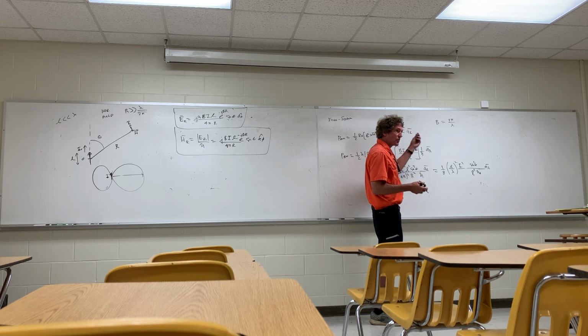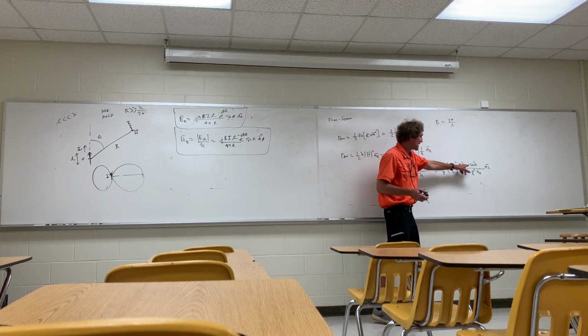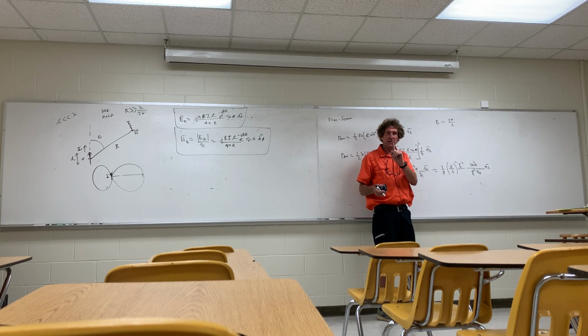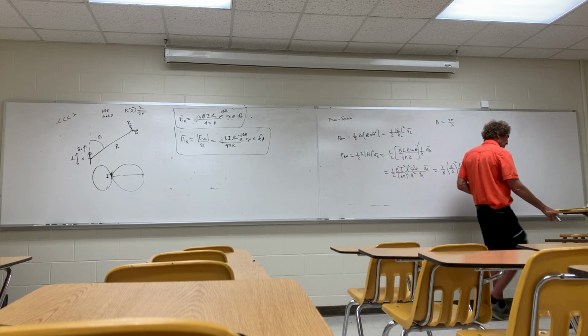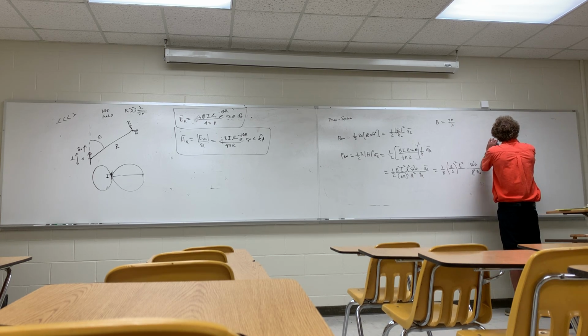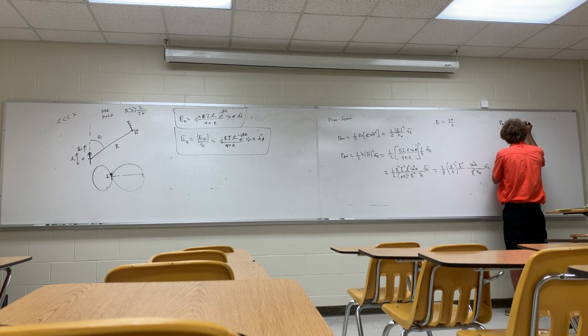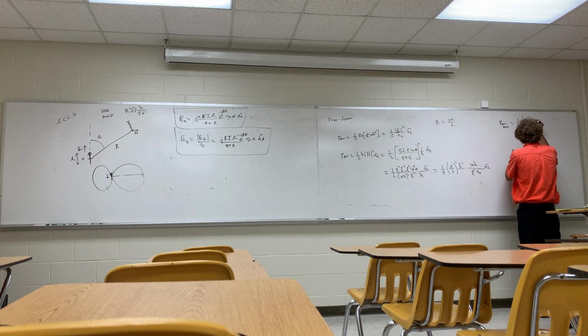At a given distance r, what is the maximum power density? So we're going to assume we're at a given distance r. Well, it will be when the sine is equal to 1, right? It will be at 90 degrees. So now we can say that the P max for a given r, P average max, is just going to be these terms, which are 1/8 times L over lambda squared, I squared over eta naught.